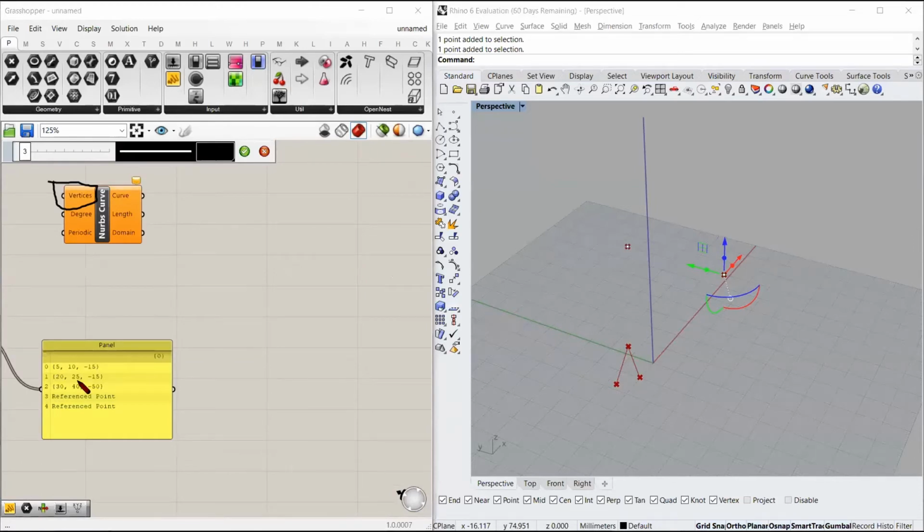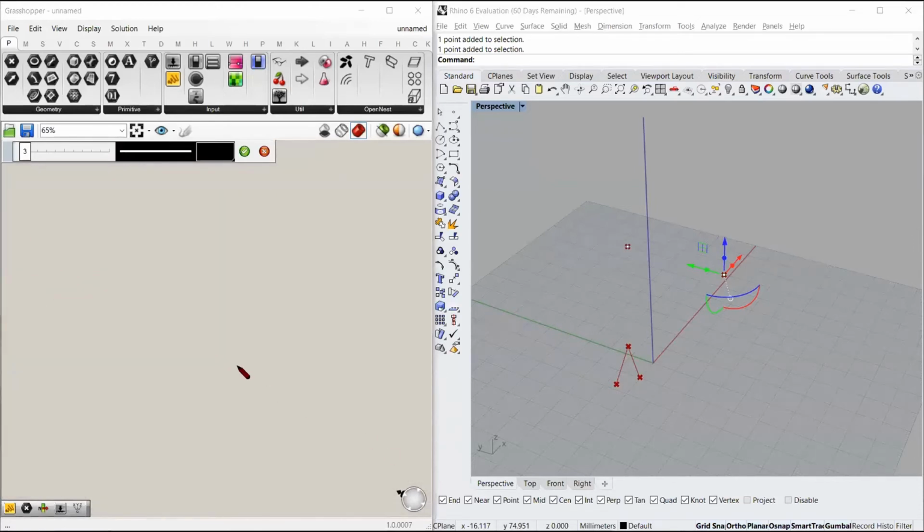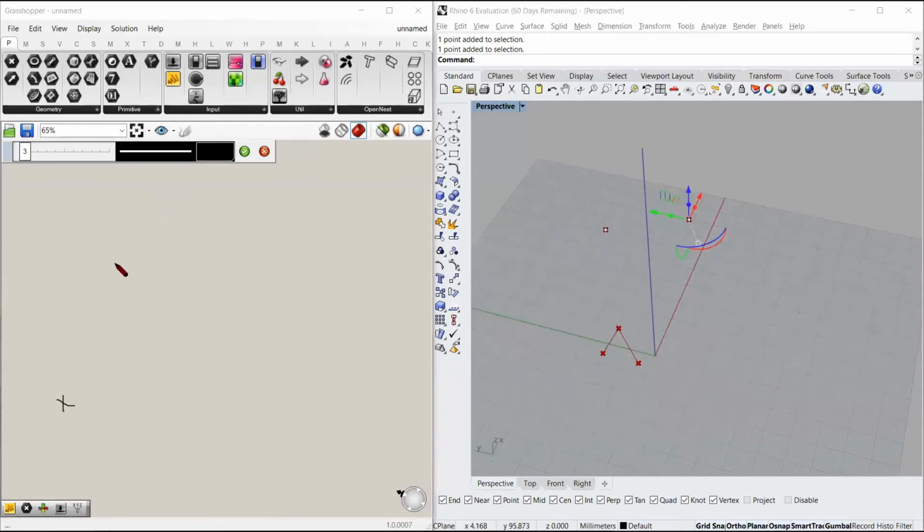Suppose I have this point, I have this point, and this point, and the last point, and I try to make a NURBS curve. It would make something like this, where these points are controlling the curvature of this curve. Now by default, the degree of all the smooth curves is 3. And by degree, I mean degree is something that actually controls the smoothness of a curve.